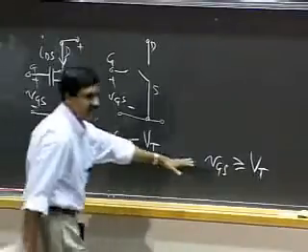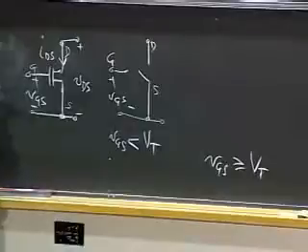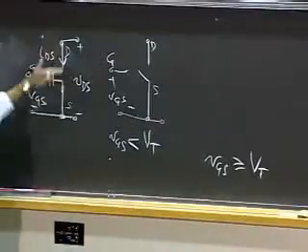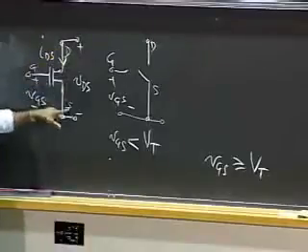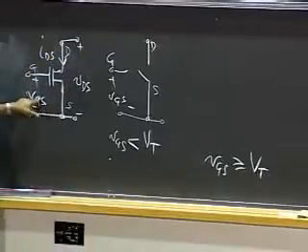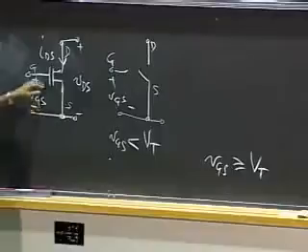Okay, so when VGS was greater than VT, we said that a simple way to approximate MOSFET behavior was to view this as a resistor connected between the drain and the source. That was our SR model used for the MOSFET. Okay, it turns out that